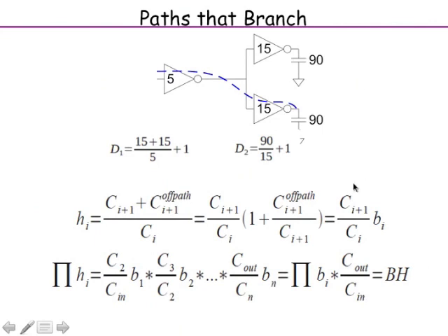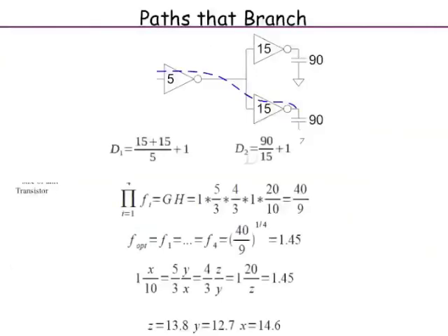So if I have circuits where there is this symmetry, where I have copies of this gate of the path, then you can just look at it and write the overall effort as B times H, where B is the degree of branching. But you can do that in special circumstances when you have symmetry like this. Otherwise, you just go back to the basic equation. For every gate, you see the C out by C in plus the parasitic, that gives the delay, and you set up the equation for the whole path and then you minimize.